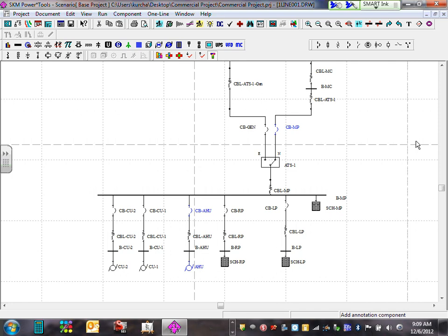Before I go anywhere else, if I have a short circuit in the air handling unit, which circuit breaker do you want it to trip? This one. If the main trips, you didn't do your job, right? That's what I'm trying to prove. So all of them are selected. So let's go coordinate. Hit that curve, coordinate.